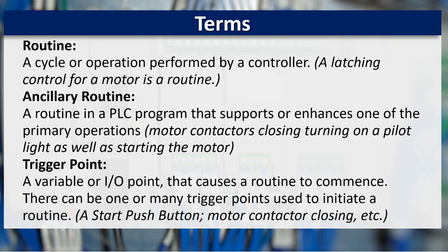A trigger point is a variable or I/O point that causes a routine to commence. There can be one or many trigger points used to initiate a routine. A start push button, a motor contactor closing. These are trigger points.